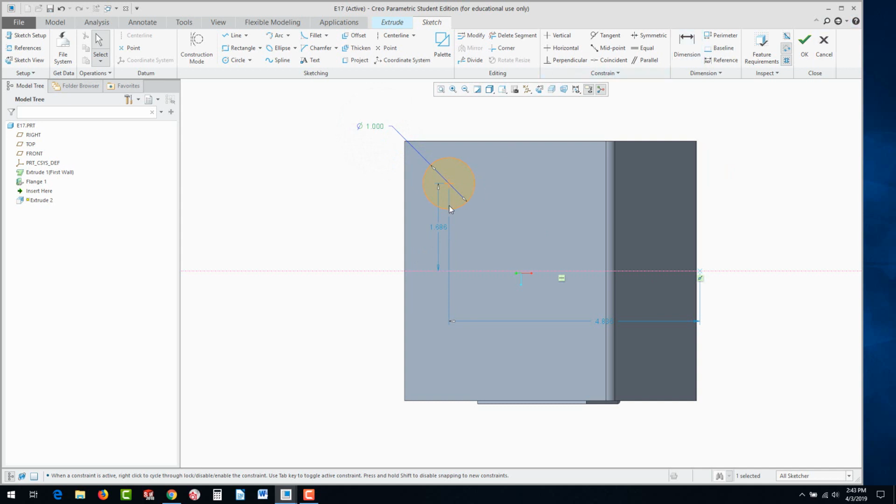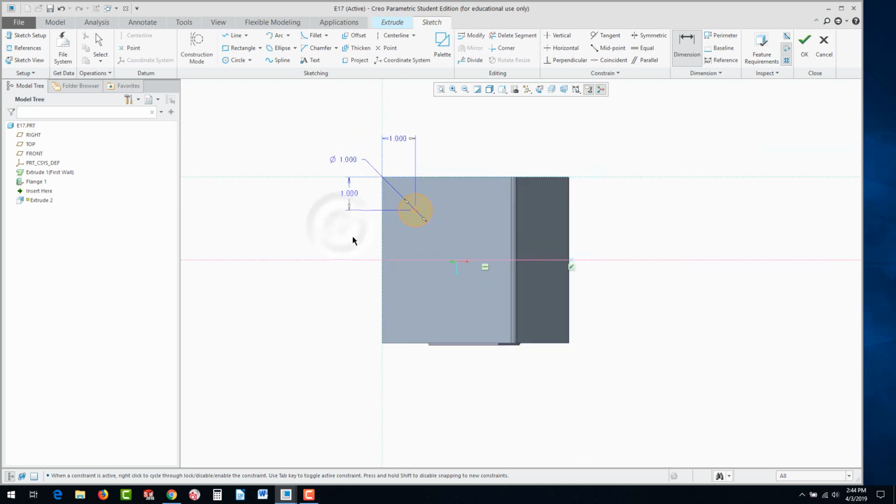And then as far as dimensioning, I don't like any of those dimensions that it's given me, so I just go to the dimension tool, select the center point to this top edge, move over here to the left and middle click, we'll offset it 1 inch, and then click on the center point to this front edge, get in this vicinity up here, middle click, make it 1 inch. Now middle click 2 times to get out of any other tools, and select the circle that you want to copy, go to the mirror, and now select the center line that you drew.